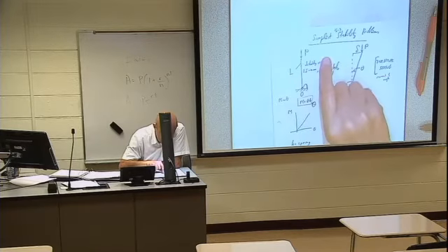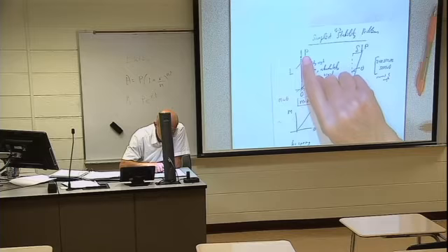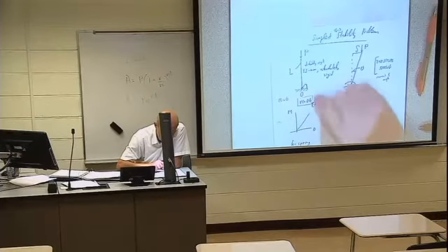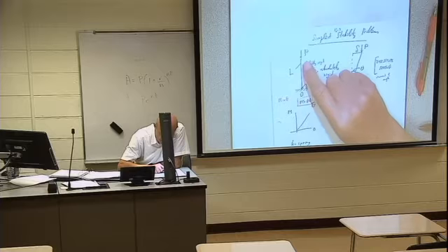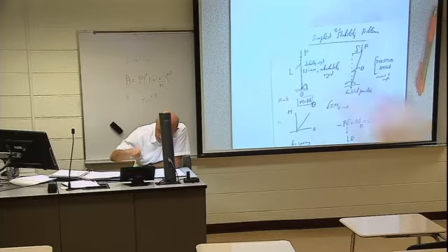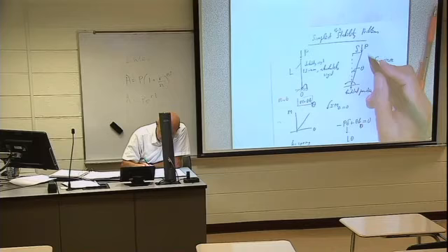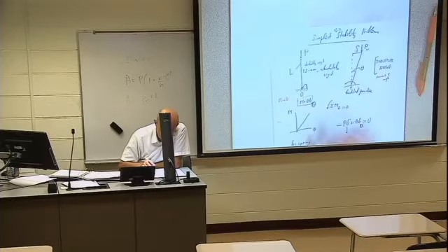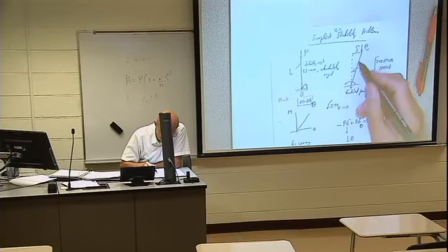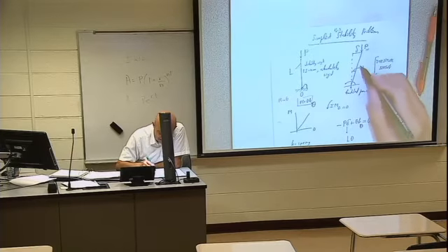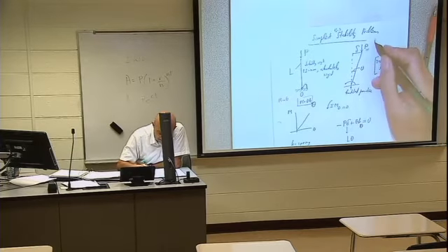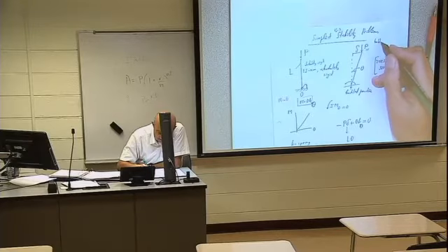We take out this kick and the beam again comes to the original position. There will be some time when I give the kick, when I increase the load sufficiently, and this load will be some critical value. Then this beam does not come back to the original condition. So I am depicting this beam in the buckled state.